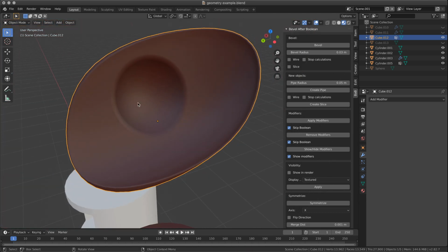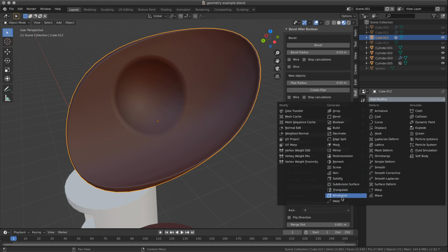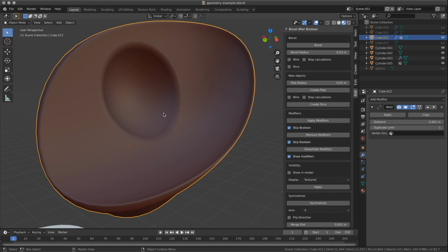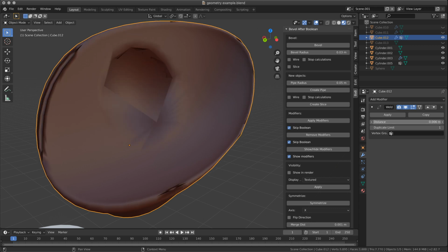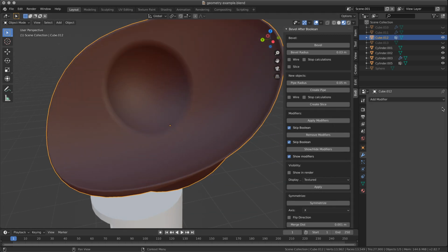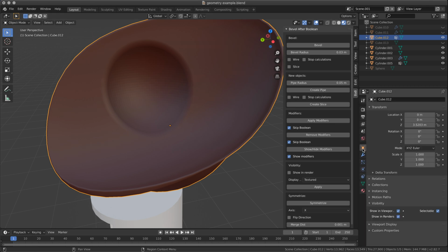What I want to try is actually reduce the geometry using the weld, the new modifier in Blender. Yes, they were in the sphere used to cut. Let's see with the weld what happens if I increase this. That's too much. Strangely enough, it's not caring about... I'm pretty sure I have a vertex group here.